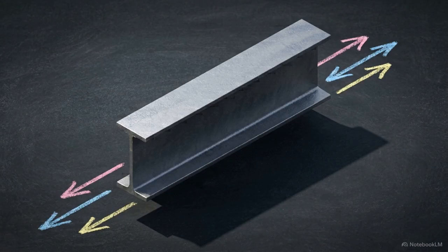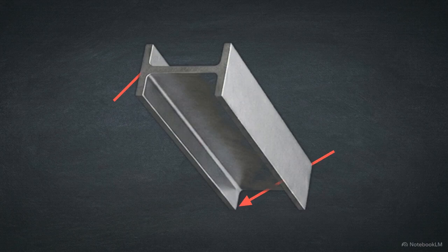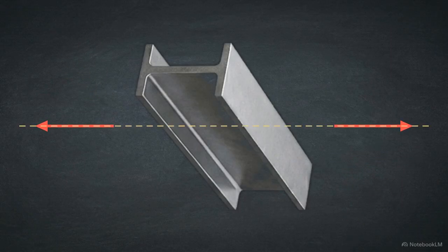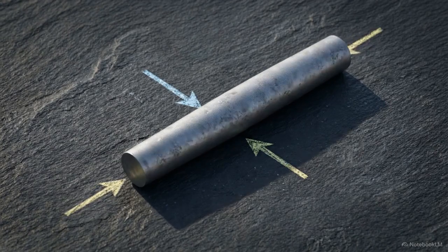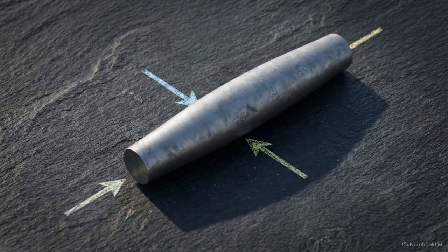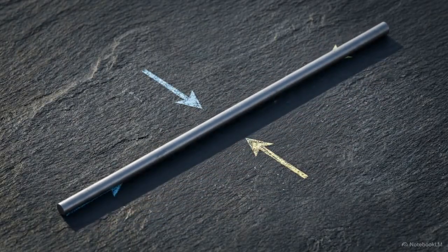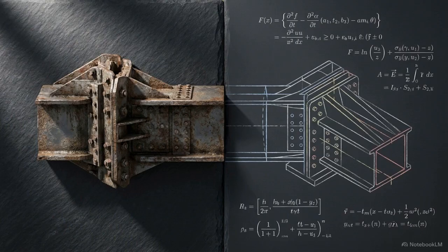When you apply these assumptions, every single beam mathematically reduces to a two-force body. The logic dictates that if only two forces act on opposite ends of a rigid bar in equilibrium, they have no choice but to be equal in magnitude, opposite in direction, and perfectly collinear. Because of this strict alignment along the axis, the member experiences pure tension or pure compression. Bending moments are entirely eliminated from the math. These extreme idealizations are deliberate abstractions. They take infinitely complex structural networks and render them solvable.